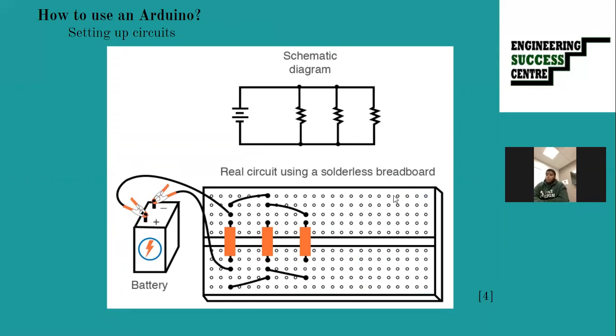So how breadboards work, they're just a bunch of connection points, but they're connected in a specific way. Because of the orientation, I'm just going to say vertical, all the pins in the same vertical column are connected. Except not across this space, just on either side of this double line, they're connected together.